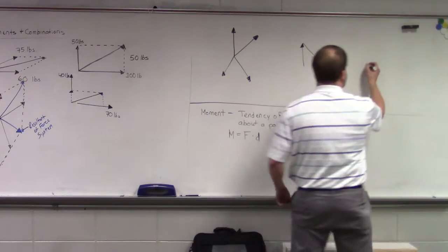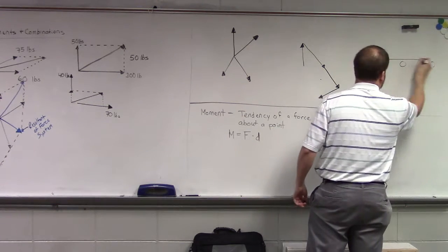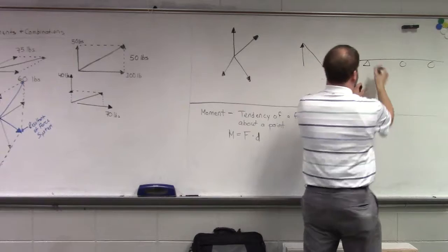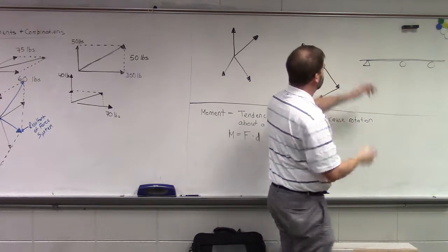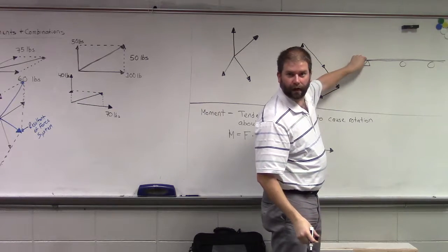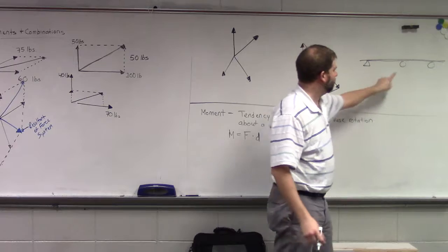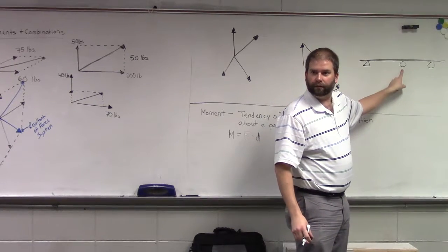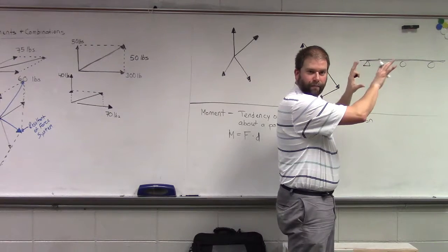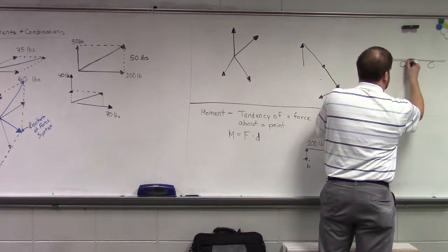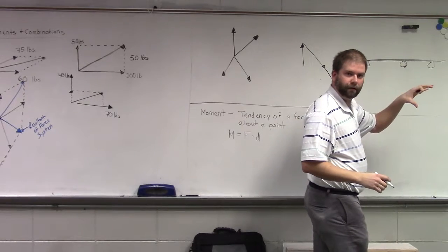So what we'll actually do is our bridge deck will be secured. It's a terribly drawn bridge deck, sorry. So we're secured here, right? So that pins our deck into place. Can't go anywhere. The roller supports it, but in the summertime, as the material expands, our roller will rotate slightly, right?